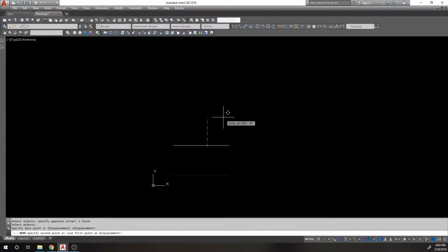So what are point filters and how are they similar to snap tracking? I'm going to turn snap tracking off to make full use of point filters. Point filters are also ways to line objects up. When you're working in 2D, they kind of seem repetitive and take much longer to operate than snap tracking. They really start to shine in 3D and become an almost integral part of accurate 3D modeling. They can increase the accuracy of your 3D models incredibly.